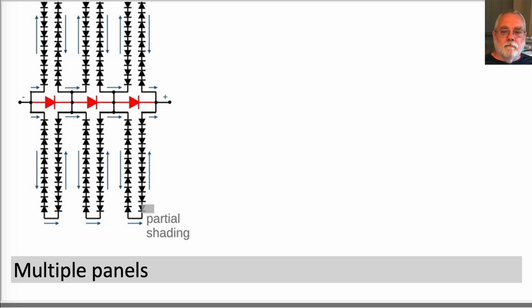Multiple panels. For a multiple panel system, use of per panel microinverters or DC power optimizers allows each panel's power generation to be optimized to its optimal power point in real time for its present illumination and shading. This is desirable, but adds to the cost and adds components that could fail eventually, fail on your roof. A cost-benefit analysis should include the labor cost of replacing potentially failed electronic units, for example on a roof, over the lifetime of the system.